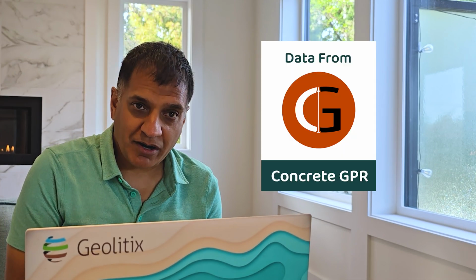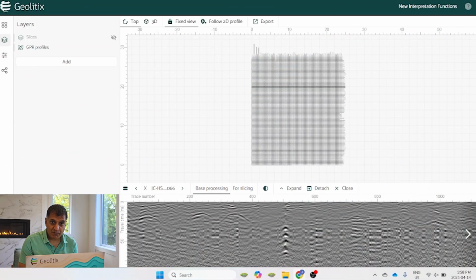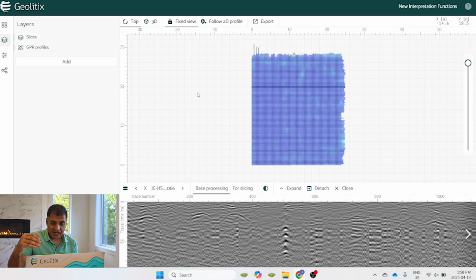It comes to us from our friends at Concrete GPR in Portland, Oregon, and it is a dense data set. There's a line every 1 foot in both directions. This is a 350 megahertz GSSI antenna. I'm just going to turn on the slices here. I've already made these, and I've also pre-processed all this.